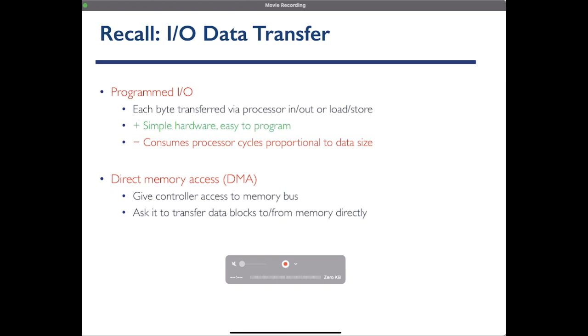So the alternative is direct memory access, as we talked about. With this one, the driver sets up the data transfer. Let's say you have a GPU and you want to transfer 1 GB of data and then let the GPU do calculation on the data. You usually do that through DMA. You don't want to send each byte of data using load and store from the CPU.